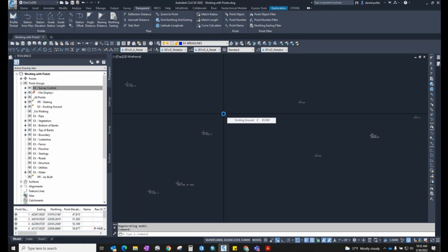It gives you a point of reference when you go to implement. So if I did this survey this year, and they don't do the construction until 3 years from now, and I have a plan view with no TBMs located on it, unless I actually opened up CAD and looked at the drawing, I would have no idea where these TBMs are, because I can guarantee the stakes are not there. They're usually gone within a month or so. So you have to have some type of reference based off of that drawing. I like to see the TBMs on our plans at a minimum. I don't know if anybody else is on here that reviews plans, but this is something that should be on there at a bare minimum.